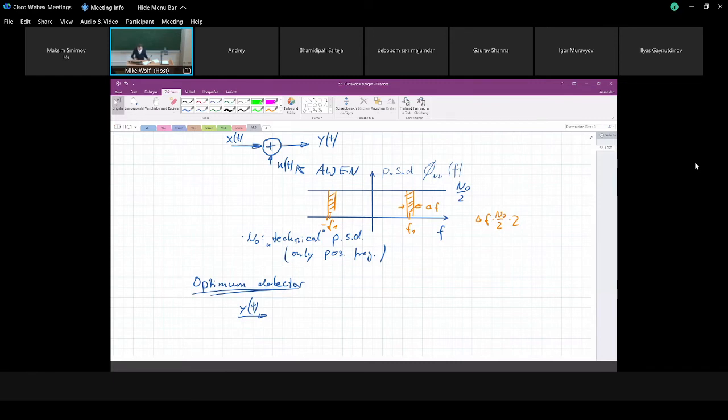And this consists first of a matched filter, and the impulse response of this filter is g of t equal to, I assume here non-causal filters, psi of minus t. This has something to do with optimal detection, and we will discuss this in communications engineering, okay?